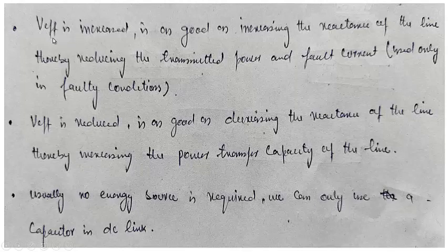This condition is met when this voltage is inserted in series, but it will be leading the current by 90 degrees. In this case, this voltage will be inserted in such a way that it will be lagging the line current. And since this voltage is controlled by the converter itself, it will be independent of the magnitude of the current, as was not the case when we use capacitors directly, because their reactive power will be dependent upon the current flowing through them.